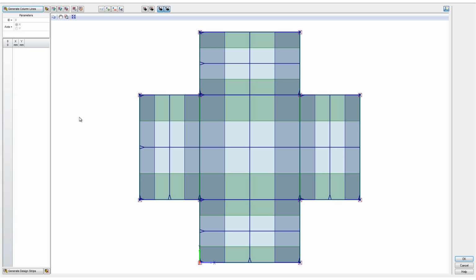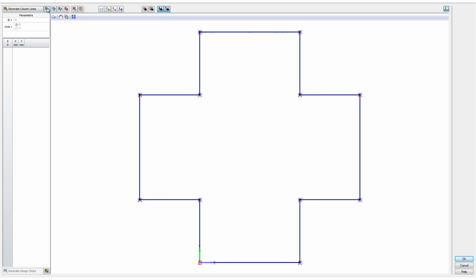The new assistant presents a 2D interface of the contour of the slab. The new menu allows the quick generation of the design strips in two different axes of the concrete slab. We will now generate the design strip for this short example. The automated generation is done based on the support detected in the model. The supports are then represented by these boxes with an X in it.